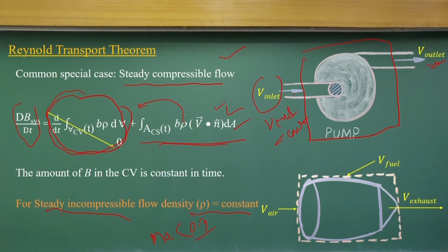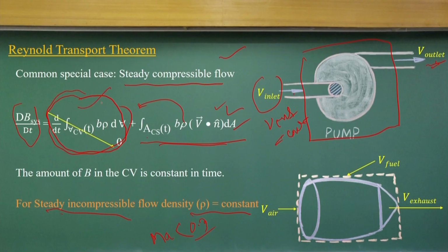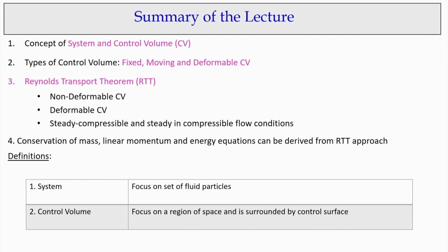What I want to emphasize is that the student has to understand how to simplify problems: whether to solve the problem as a steady compressible flow or a steady incompressible flow, or as an unsteady compressible flow, where again you have to do a volume integral. Simplification matters a lot in solving the problem, compared to using advanced mathematics. I will try to give a lecture on how you develop the art of simplifying complex problems using the control volume concept.